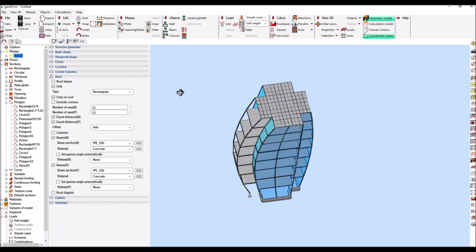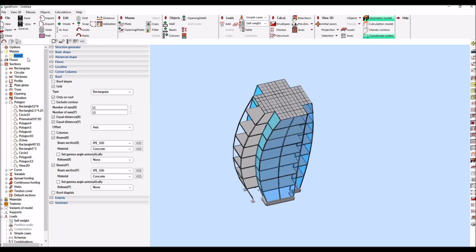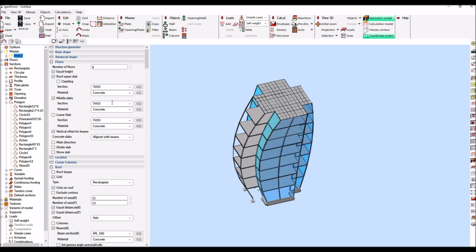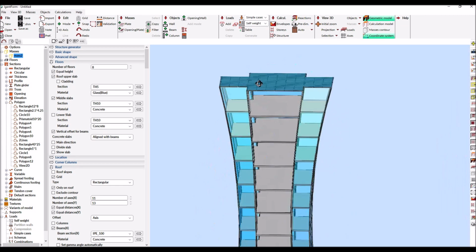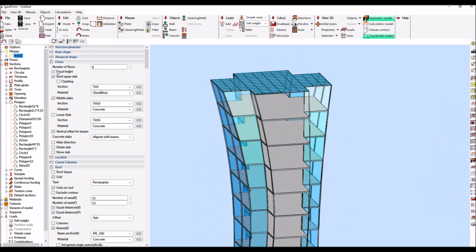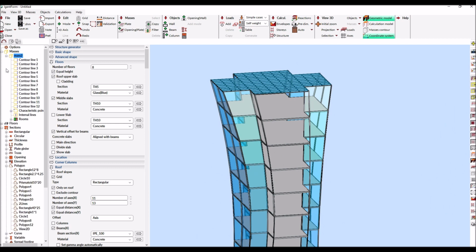Beams can be assigned any cross-section previously defined in the cross-section database, including trusses. Individual groups of parameters can be freely collapsed or expanded at any time, focusing on a selected part. The next step is to determine the parameters of the upper plate. In this case, we change its thickness and material.